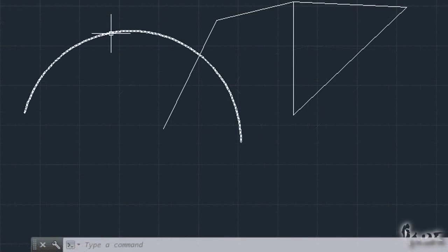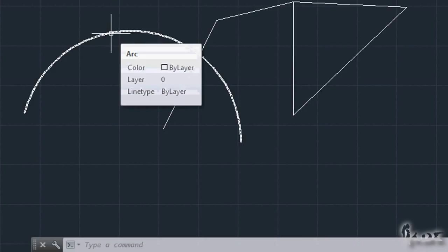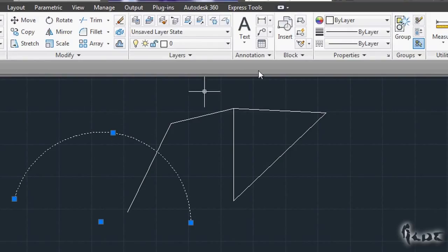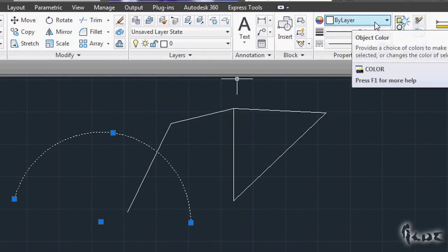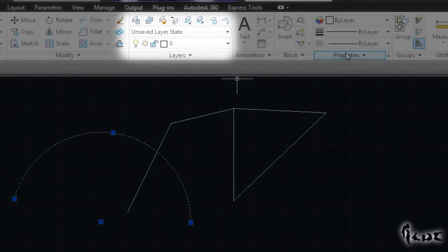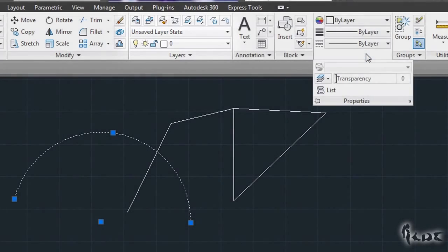Let's now see how to manage and edit objects. If you leave the pointer on an object for some time, you will read the info about it, especially the layer it belongs to. Each layer is recognized by a different color and used to find all its objects more easily inside your project. Under the section Layers, you can manage all of them fully. However, I'm not going to explain them in this tutorial for beginners. You need them when a project starts to be complex.